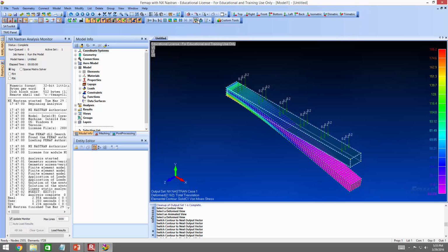To give you a quick preview of what I'm expecting for the analysis project, you're going to define a problem in engineering that needs to be assessed. Let's say, for instance, it's the deflection of a beam that has a weird geometry. You're going to run a model using the same modeling technique as a benchmark problem like this. Let's say you're going to do your problem using brick elements. You're going to run the model using different mesh densities. Remember how we did 0.5? Maybe you do 0.1, 0.5, and 2, so you have a really coarse mesh and a really fine mesh.